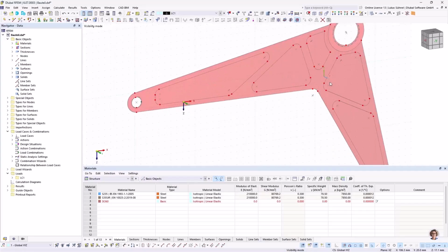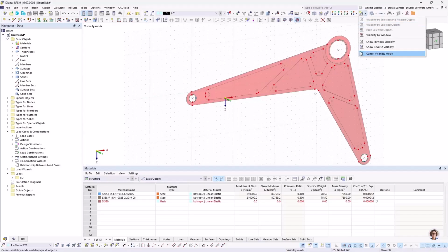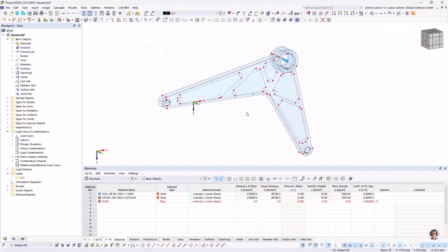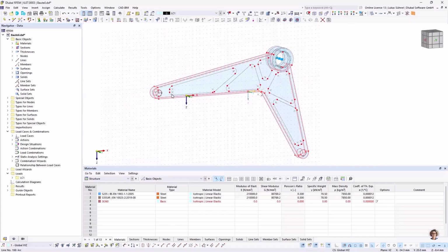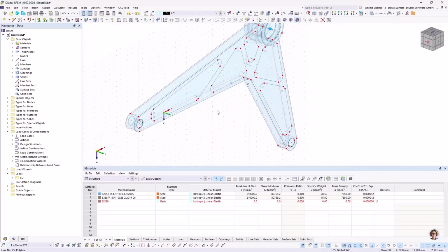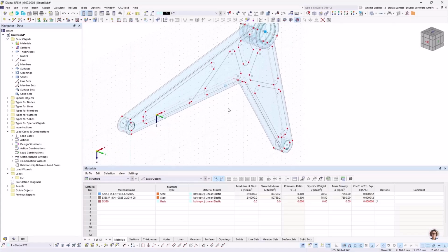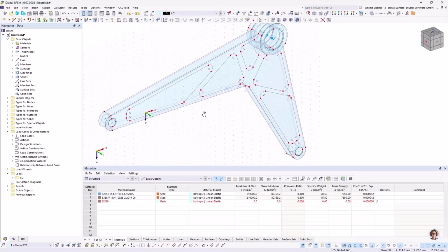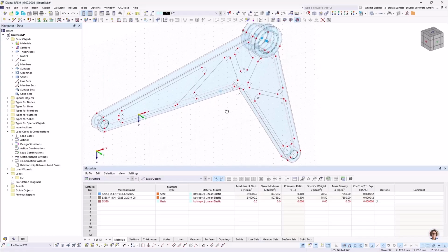Now, these are my surfaces. I can show the complete structure again and model actual surfaces based on these boundary lines. Why do I want to do it? I would like to create a solid for those surfaces which is reaching into this structure, and then I will use a Boolean subtraction of solids feature like that, to create these reduced areas.